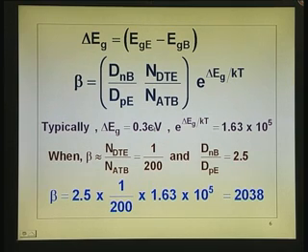Delta EG, we can get 0.3 very easily. You can get 0.3 even with the aluminum content much lower. You do not have to go to x equal to 0.4; even much lower than that, if you take delta EG 0.3, you can very easily get a wider band gap. Then e to the power of delta EG by kT, that is 300 millielectron volts divided by 25 millielectron volts, e to the power of 12, is about 10 to the power of 5.